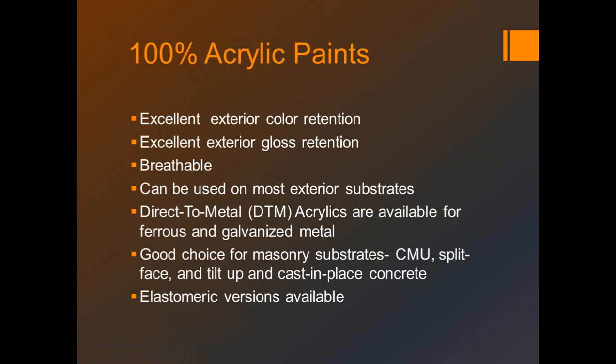I'm kind of old school when it comes to this kind of thing because I'm a primer to finish coat kind of guy. That's one of my favorite methodologies to specify around. You do get some benefits in prime coats, and with the DTM primers, some of them have rust inhibitors in them, some of them don't. You need to be a little bit careful about that and make sure you're looking at the data page and asking the questions. But if you do put a prime coat on there, you're normally getting extra coat of rust inhibitive value on that surface.